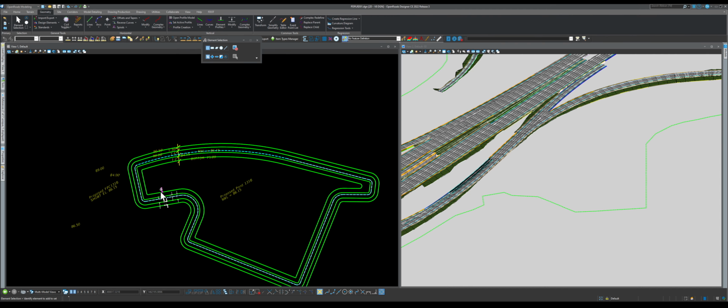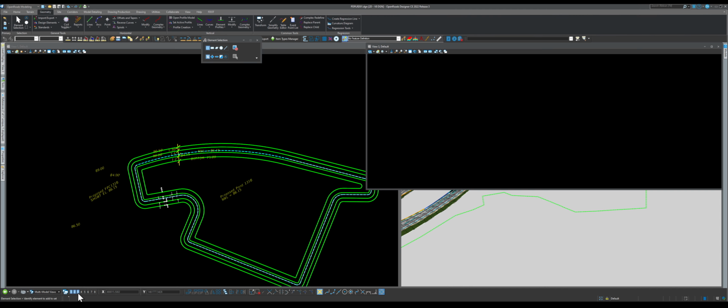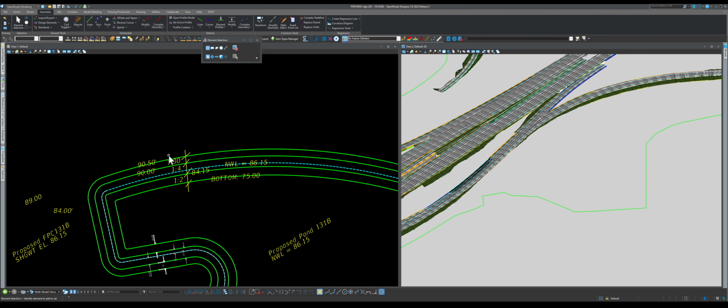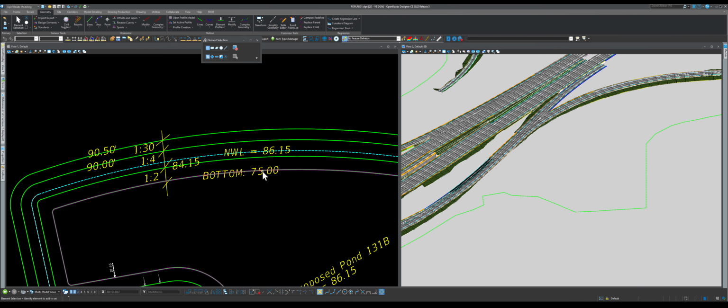So, as we know, I don't need a profile. We can use a tool. We know this one needs to be a 75, right? Remember the tool that I told you about that gave a constant elevation? Let's see if it's gonna work with this non-smart line. I don't think it will, but we'll see. So this is 75, or maybe it will. I don't know. It actually will. Cool. Okay, so if you didn't know, you don't actually have to open a profile or anything. Just do it like this and give it that.